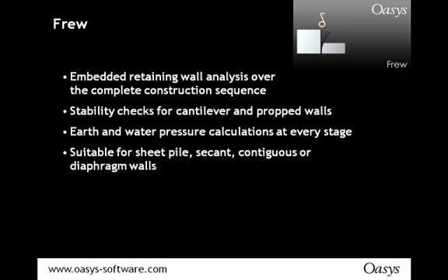And really it is an embedded retaining wall analysis over the complete construction sequence of a retaining wall. It does stability checks for cantilever and propped walls, so that's a new addition, and it considers the strut wall methodology. We've got earth and water pressure calculations at every stage, and it's suitable for sheet piles, secant, contiguous or diaphragm walls.